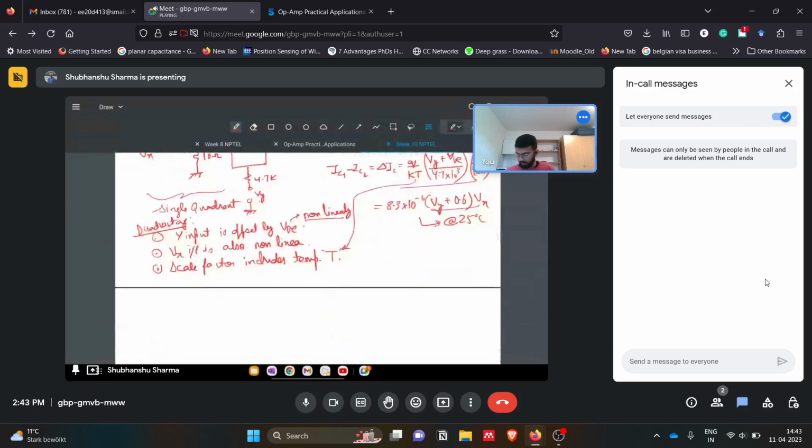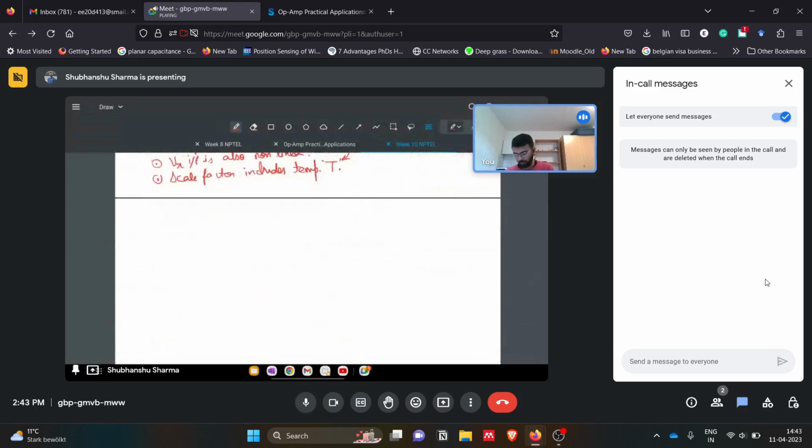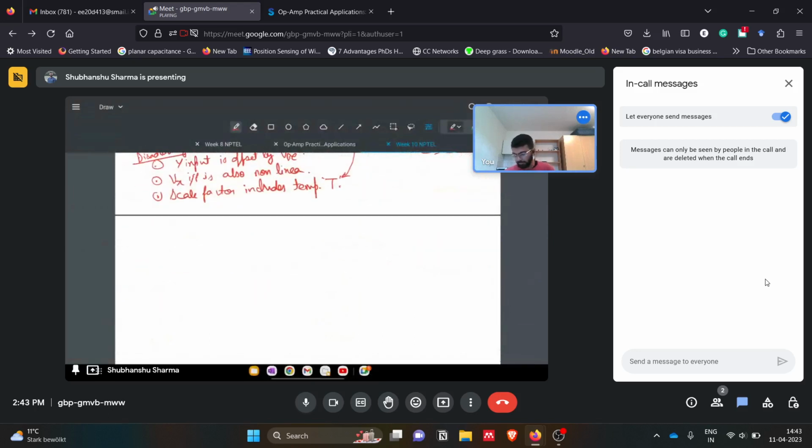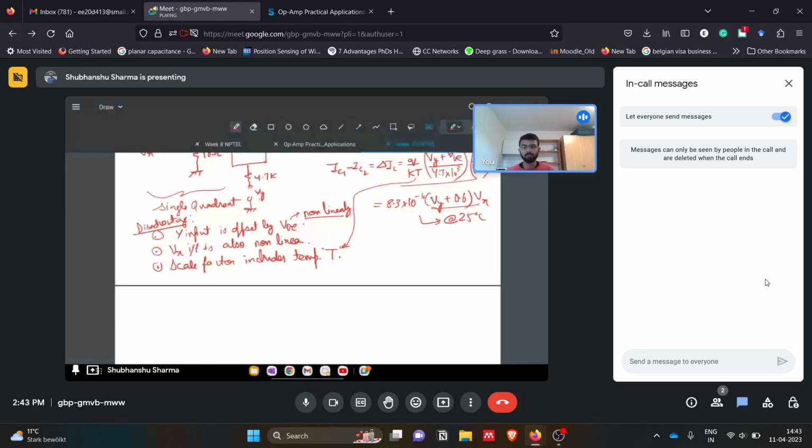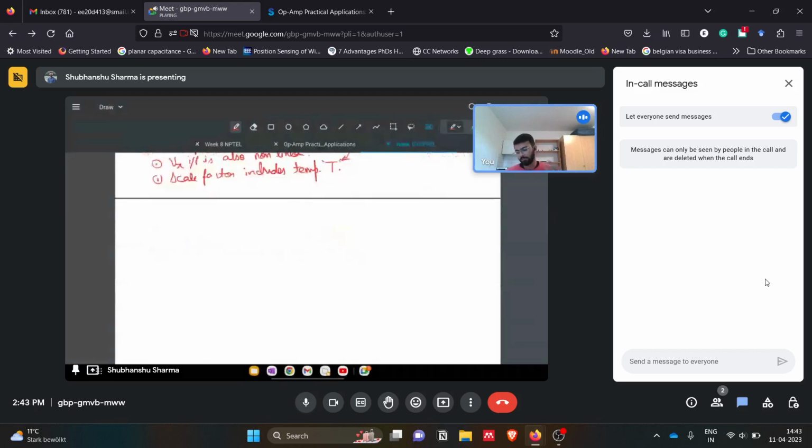But then again, there was some modification in this itself. So he proposed, he tried to multiply currents rather than the voltages and tried to get the analog multiplier circuit. So for that, he first realized a dual quadrant multiplier.